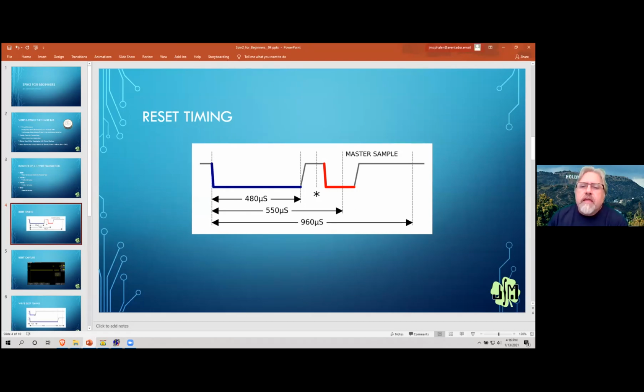If that was the case, the bus would never be high, and this presence pulse would be a false positive. So what they do, and suggest others do, is sample the bus right here. This is about 10 microseconds after you release the bus. It should have gone high again, and look to see what it is there, and then do the normal presence sampling, and then return that 2-bit value. And you can see we do that in the code.